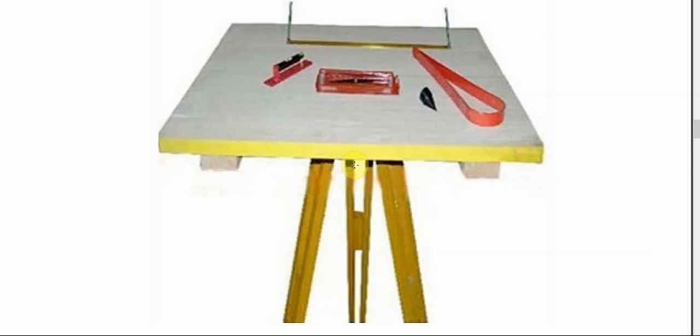But in coast survey table, leveling of the plate table can be done very accurately and quickly with the help of 3-foot screws. Now, the table can be turned about the vertical axis and it can be fixed in any direction very accurately with the help of clamp and tangent screw.